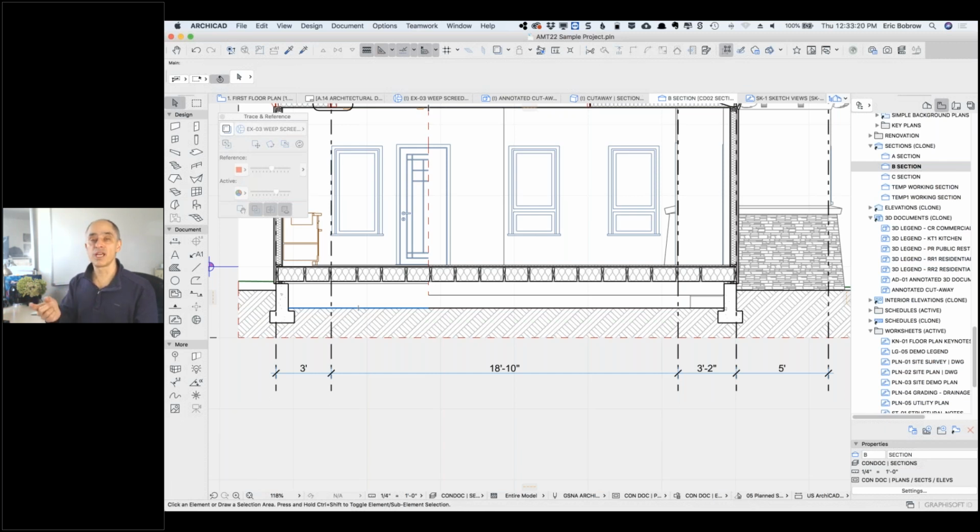Now, if you have things with the same name, then it can get a little confusing, because when you're pasting your project into this, and you have something called exterior wall type 1, and there's one already that says type 1 here, it'll basically say, oh, I know what that is, and it'll use the one that's native here. So you could have some changes there. One of the things that I did, again, subtle stuff, is to make all the attributes for surfaces and composites and building materials all at a higher index number, so that it's easier to see and organize your stuff.